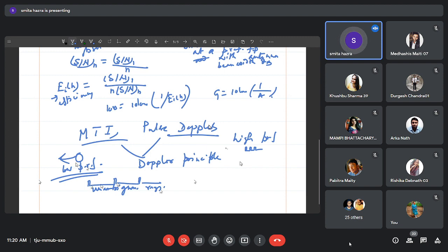Similarly, delayed echo for the second pulse or the early echo from the third pulse. Clear? If it is a delayed echo, then obviously it is coming from a long distance. If it is an early echo, that means it is coming from a near object. So from this operation, you are not very fixed about the appearing range. So range information is not very correct from the high pulse repetition frequency.